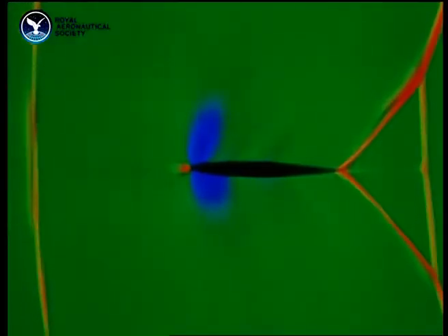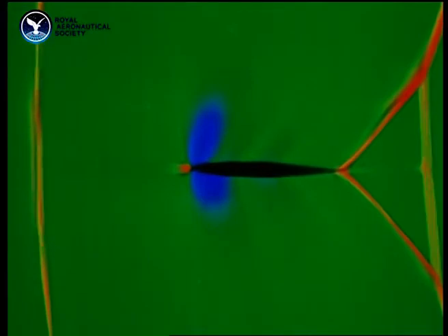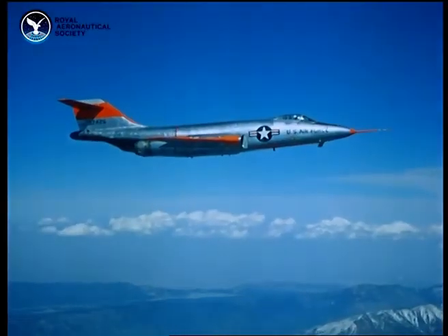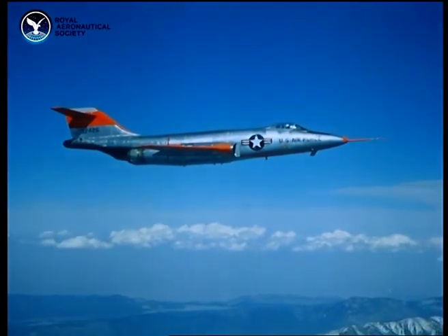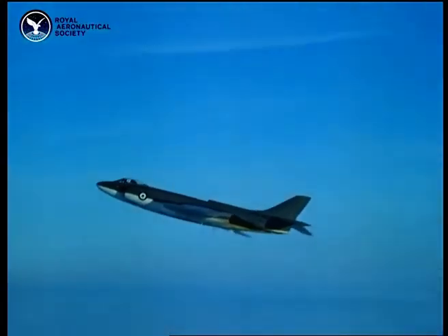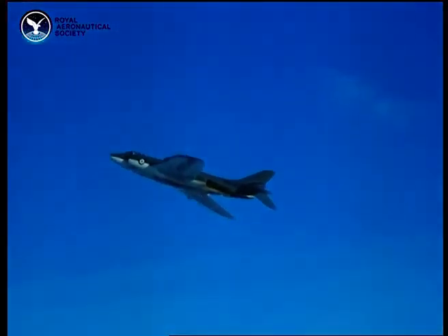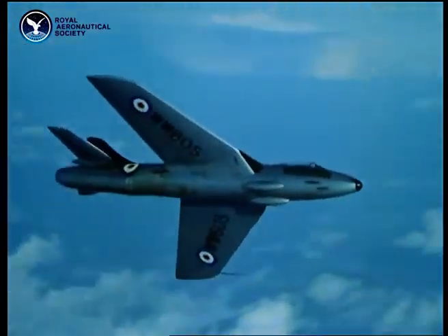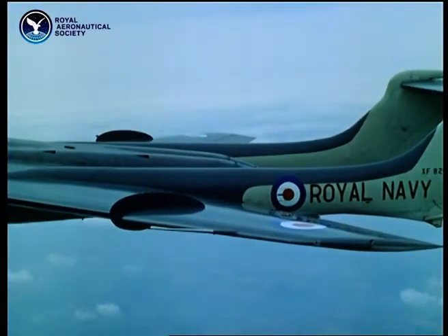Above Mach 1, the bow wave adds its own drag. This can be reduced by having leading edges and nose sharp rather than rounded. Compare the effect on the bow wave of sharp and rounded leading edges. In these ways, designers are gradually solving the problems of transonic flight and building aircraft that are safe at high and low speeds.